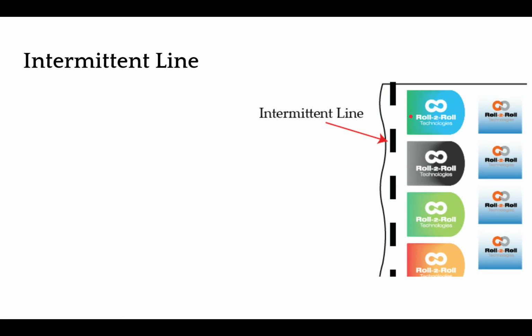And one of the things with line guiding is that when you don't see anything, there's no way we would know which direction to move, because the pattern could be on any side. In an edge guiding application, if you don't see a web, then you know you need to go this direction so that you can see the web. And if you see the whole web, then you need to go the other direction so that you don't see the whole web. In edge guiding, we know that, but in line guiding, there's no way of knowing which direction to go if you don't see a line.